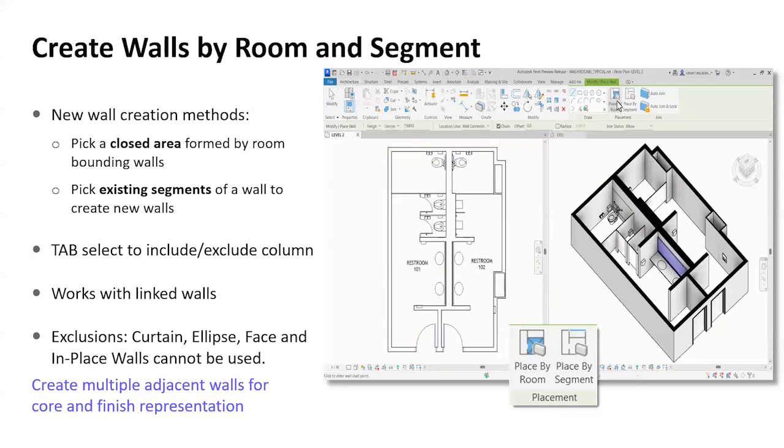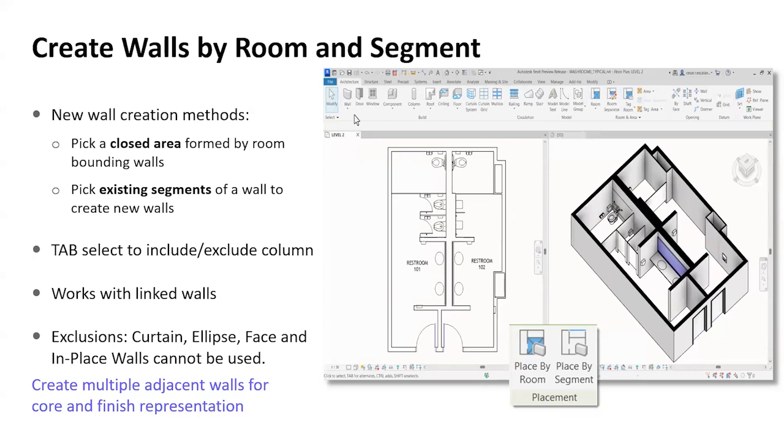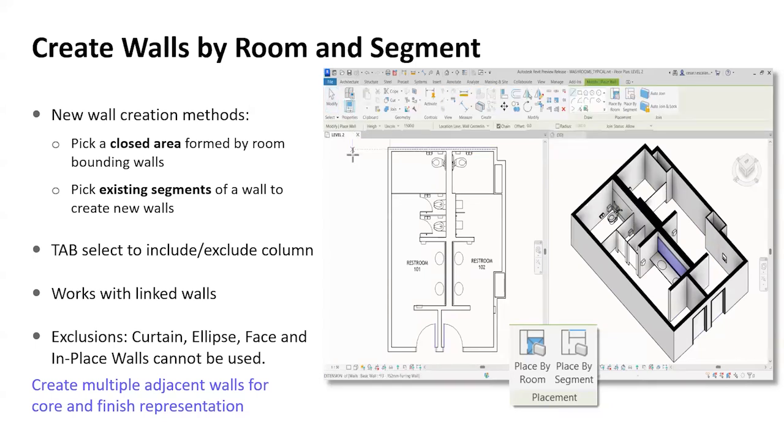The pick target may be inaccurate when there are two walls joining at a sharp angle. Like, for instance, a sharper angle at less than 32 degrees, it was problematic. Those walls are joined with the square off by default.